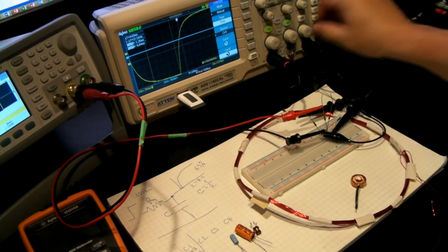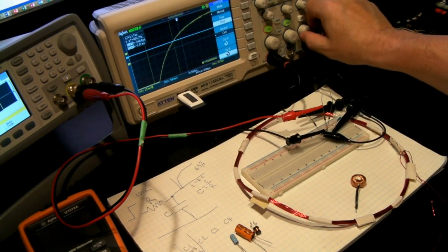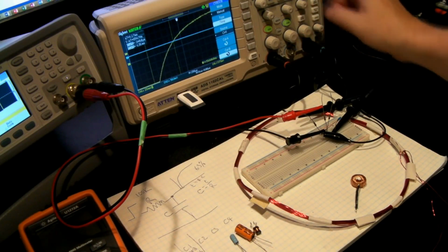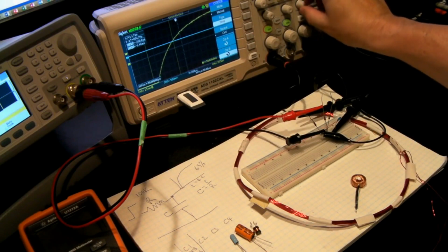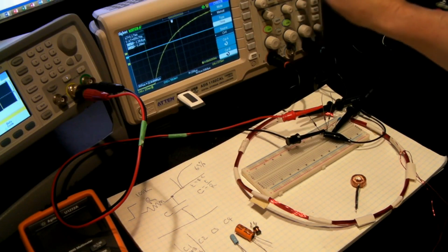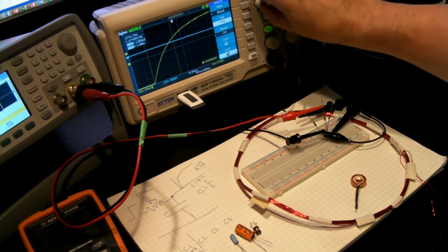So this is a higher value, and let's just now bring this out so that we can get a decent amount of the waveform there. You can see this is now not making the cursor, so we'll have to readjust this so that we do. I'll just move that onto the cursor A so we've got plenty of width available, and I will adjust cursor B so that it hits the 66% mark.